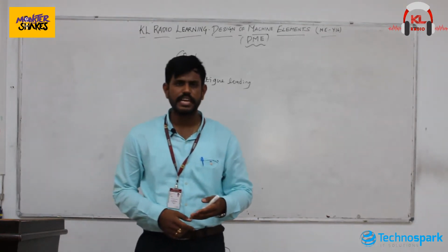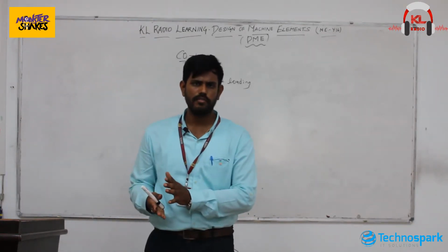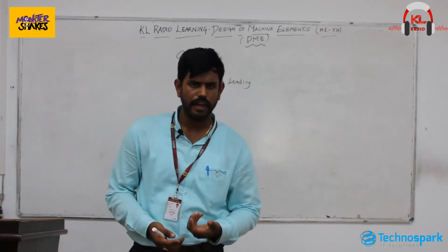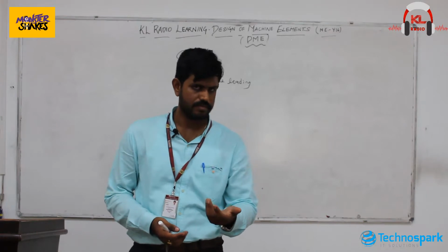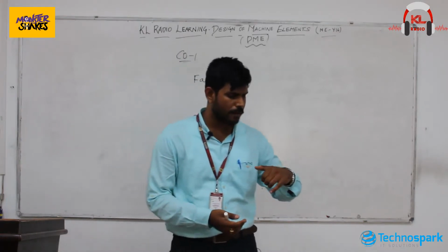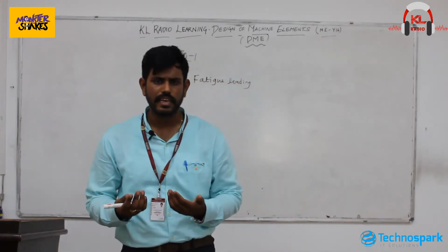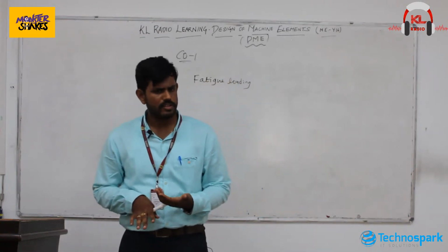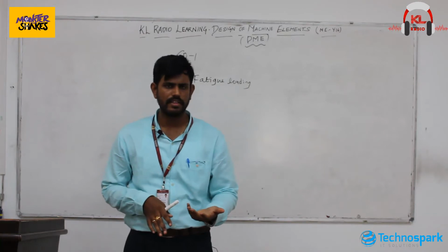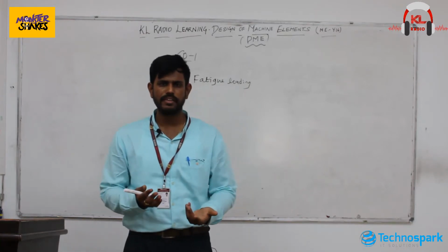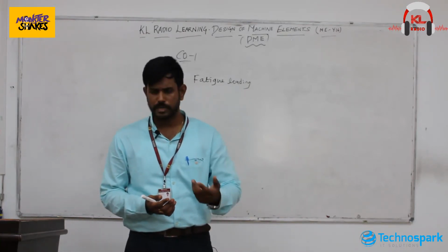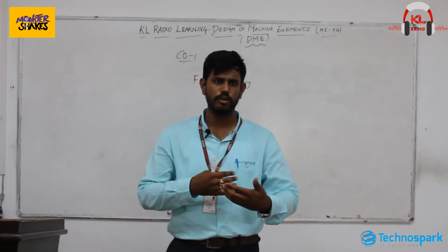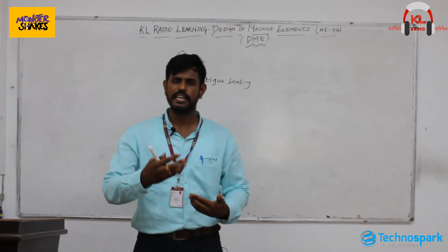As the load is changing, the failure of a component might occur much before sigma y, that is the yield. The failure of the component might occur well below the yield stress of that particular component. So this is a bad sign for a mechanical engineer, because you can't predict the failure under fatigue loading. Sometimes it might go beyond yield stress, and sometimes it might fail even without reaching the yield stress.